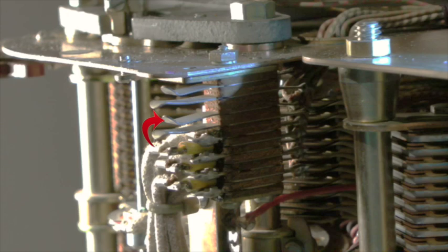The third test jack is connected to the line finder start lead. It can be used to check the vertical and rotary stepping capability of the line finder and the 11th rotary step functionality. By grounding this jack, the line finder will be seized and begin hunting for a line requesting dial tone. However, since there is no line requesting dial tone, the line finder will step up to the 10th bank level and then rotate to the 11th rotary step, release, and repeat this procedure until the ground is removed. Let's watch.